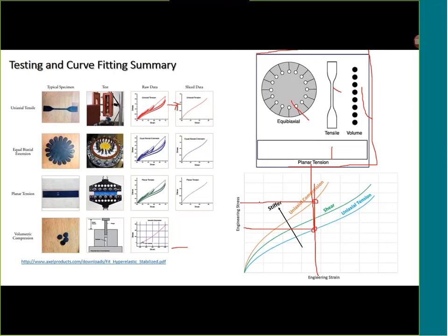It means that out of these 3 curves, a good idea to test whether the stress-strain curve makes sense is that your compression curve should always appear on the top, your tension curve should always appear on the bottom, and your shear curve somewhere in the middle. Okay, either it should be like this or it can go like this, but at no point can your uniaxial compression curve come below the uniaxial tension.